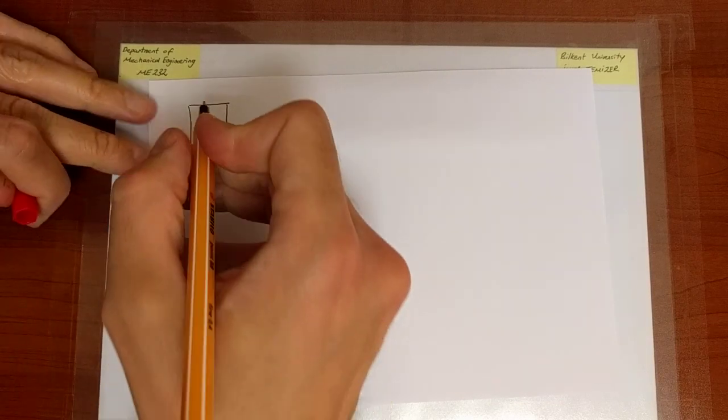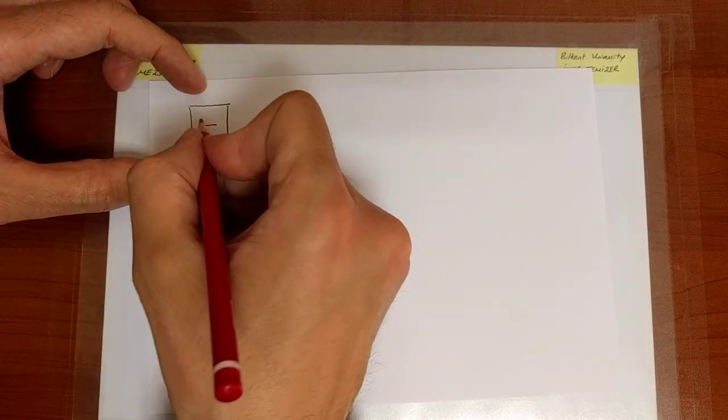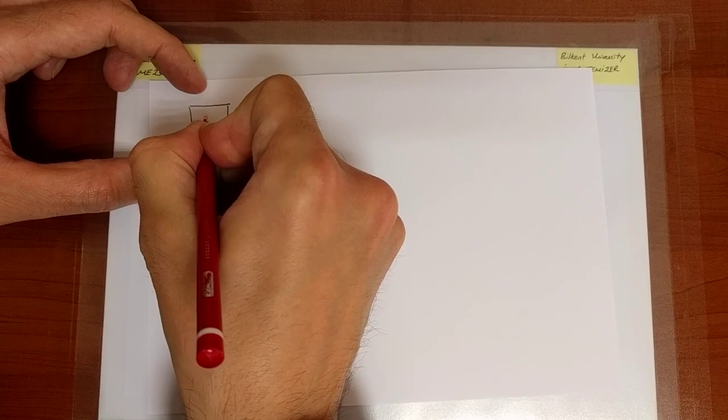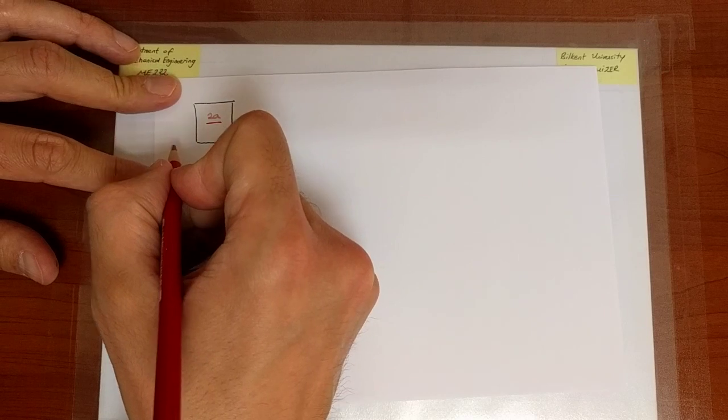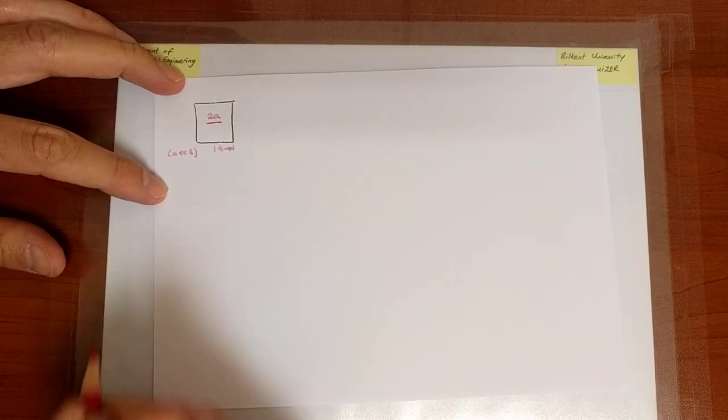the plate. And then there is a hole which is so thin that it represents a slit, or what we now call a crack. And that crack has half width A or total width 2A. We have to remember always that A represents the half width of the crack, and I have so far also assumed importantly that A is much less than B.